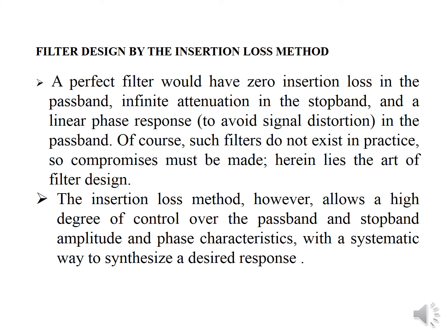Next is filter design by using the insertion loss method. Filter design using the insertion loss method is applied for a perfect filter, that is, one with zero insertion loss in the passband, infinite attenuation in the stop band, and a linear phase response. Linear phase response means there is no signal distortion in the passband.